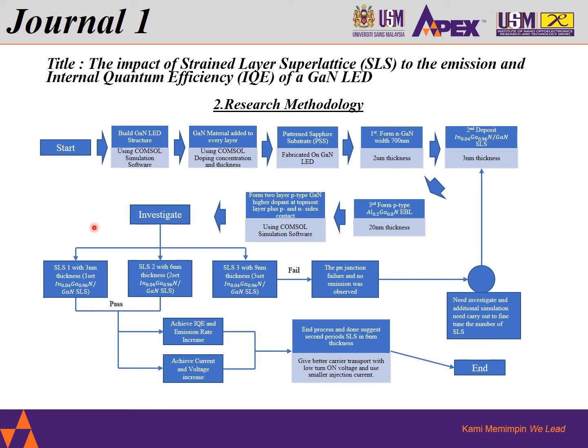With these three SLS investigations, we found that SLS1 and SLS2, with thicknesses of 3 nanometer and 6 nanometer, achieve an increase in IQE and emission rate, and also an increase in current and voltage. This suggests that the second period of SLS at 6 nanometer thickness will give better carrier transportation with low turn-on voltage and use a smaller injection current. But